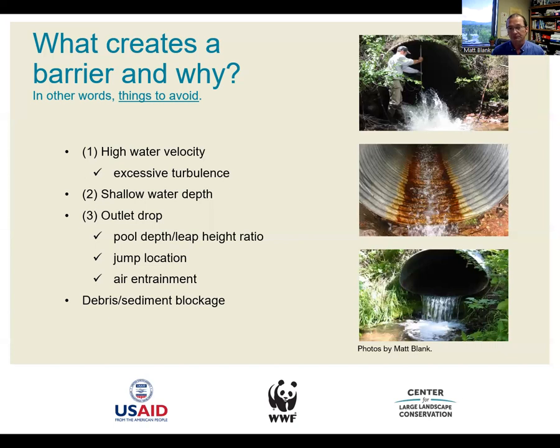through that structure. And then the other one that's equally important and is often tied in to creating some of these other issues is this debris and sediment blockage. Basically that's where the structure blocks sediment and or woody debris, or in some cases just large amounts of vegetation that move through aquatic systems, creates a dam, and then that creates a barrier.